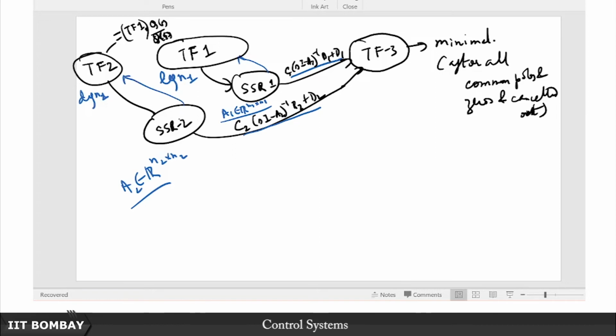When I said that earlier, you might hold me to it and say that earlier you said that if you go from the transfer function to the state space and then state space back to the transfer function, the result was the same. But we were not equipped with all the sophistication at that point to talk about it. Strictly speaking, we do not necessarily go back to the exact same form of the transfer function. You start with the transfer function, take its state space realization, and then apply C(sI minus A) inverse B plus D. You go back to, technically speaking, the same transfer function, but not exactly in the same form.